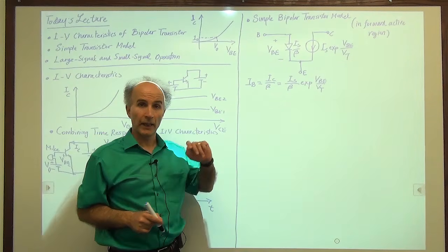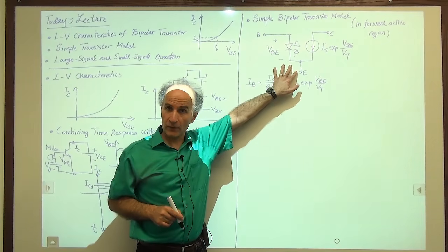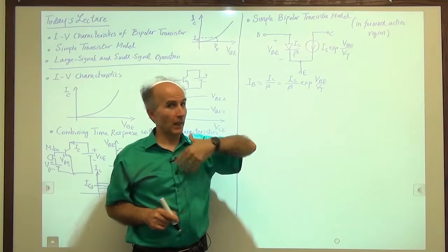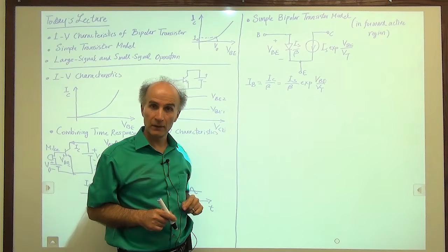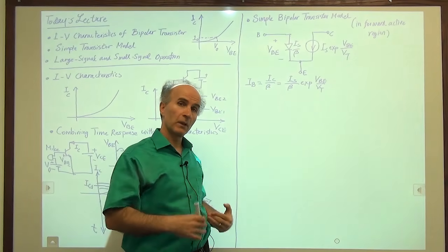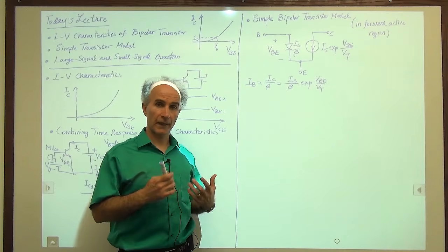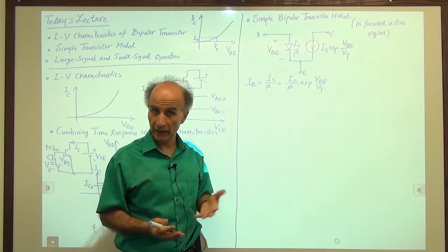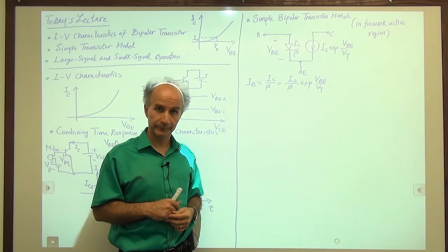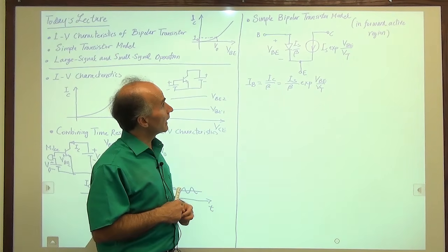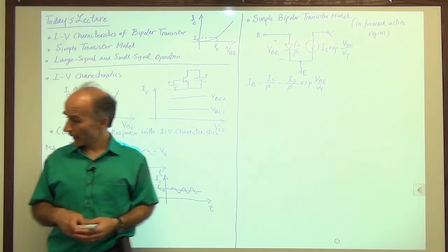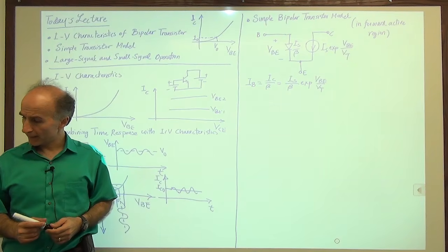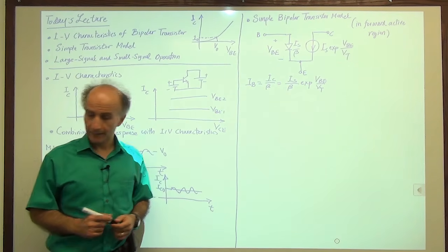Congratulations. Now, any circuit that I give you that has bipolar transistors in it, you should be able to replace each transistor with this and calculate everything, solve the circuit. Because the circuit now reduces to techniques and topologies that we know from the past, or at least lends itself to simple KVLs and KCLs, etc. All right, that's a good start, and let's start from there and go through some examples to see what happens.